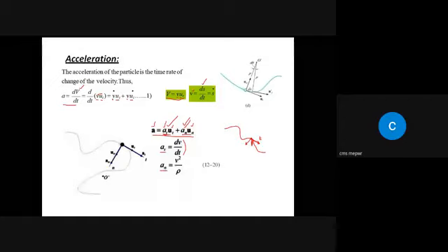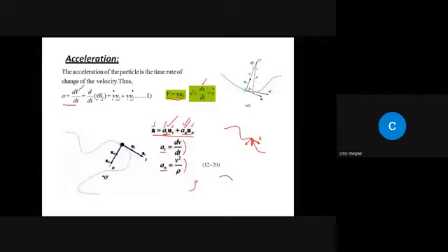Now what is this rho? This rho is the radius of curvature. For example, the particle is following this curve, and if it is following this curvilinear path, and you want to find the position of the particle at this instant, you need to find this radius. This radius is rho. If the particle is at this location, then at this location this might be the rho.